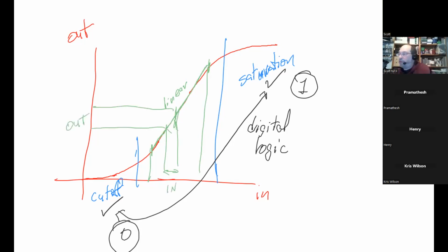In this use, this is known as an amplifier. Notice it says linear amplifier. A transistor is a very good basis for something called a linear amplifier. But if it's driven into cutoff or driven into saturation, it's not linear anymore, and it doesn't work very well. So it's very important to use the transistor in the way that it will actually function properly in the way that you want it to.